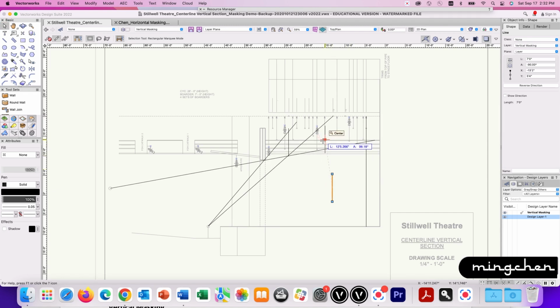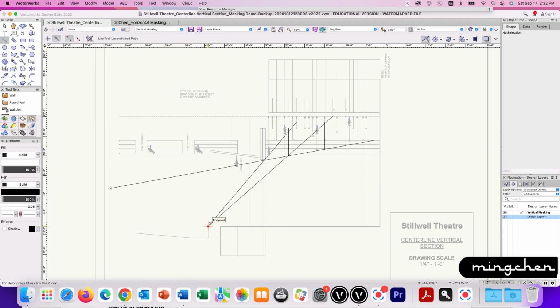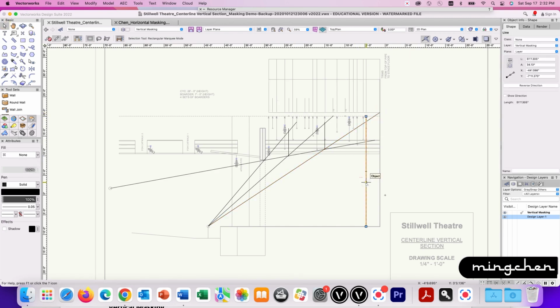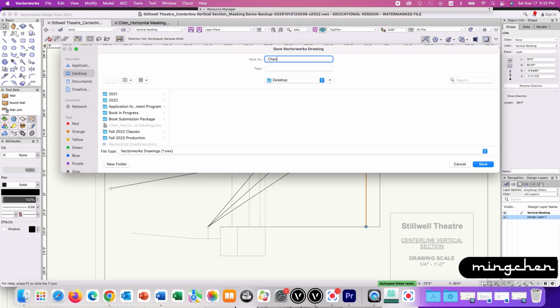In the meanwhile, block the second side line and meet the reference line that marks the onstage limit of the borders. You need to push the border to a batten position as further upstage as possible to save unnecessary borders while still blocking the second side line. Repeat the previous 2 steps as many times as needed until the borders block all the audience sidelines to the offstage space. Save your VWX file as your last name _ vertical masking.